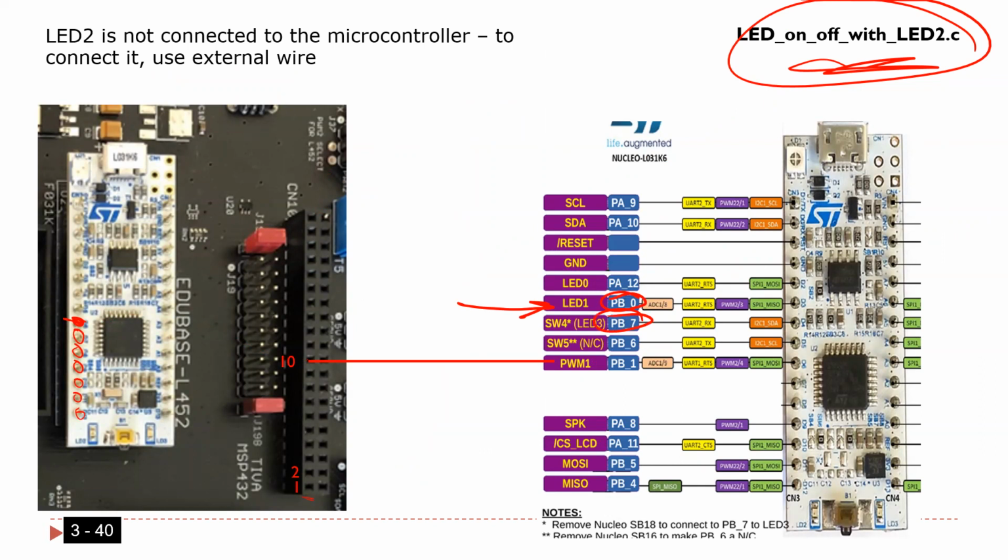And when I decided to connect this one, I just selected PB1 because this one is somehow empty. It's not connected to the speaker, it's not connected to the LCD. So I found this one very appropriate, because this one is not going to interfere with the speaker or whatever. You know what I'm saying? So again, first of all, we already used port B. All of them are the same. If you want to use A or B, it doesn't matter. You know what I'm saying?